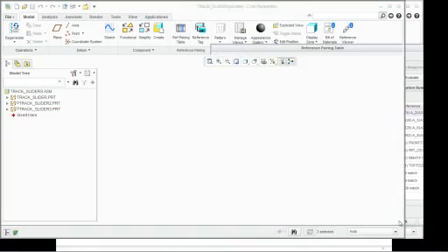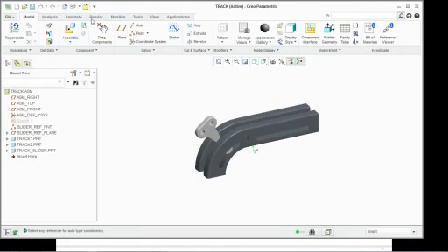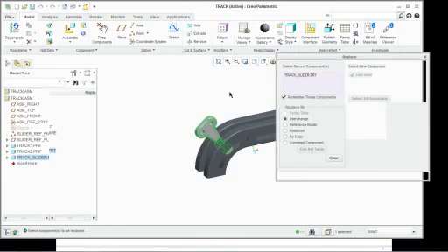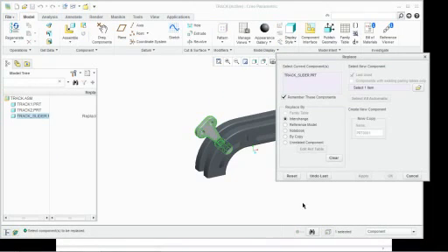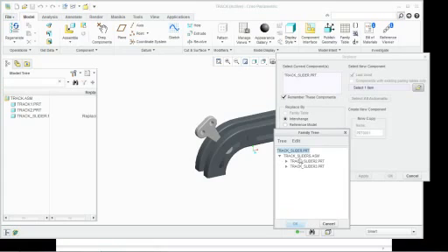So I'm going to click OK, and I'm going to flip over to my track.assembly again. I'm going to select my part, right-click, replace. Now notice I do have the option to use an interchange. When I click open, my family tree pops up, and it's going to say, what do you want to do?